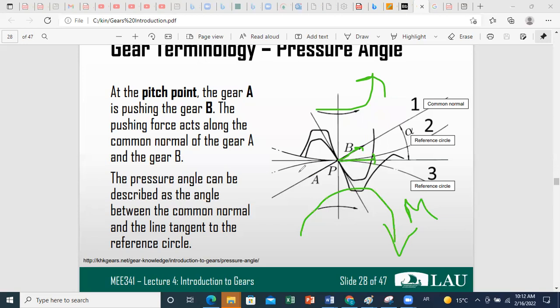Okay, so always for the gear that is driving motion, the contact force between the two gears will be an opposing force. However, for the driven gear, the contact force will be a driving force. Because look here, you need a motor to operate your driving gear. Okay, so you need to put a couple, and due to the interaction between B and A, we have seen that the force of B on A is opposite to F of A on B, downward.